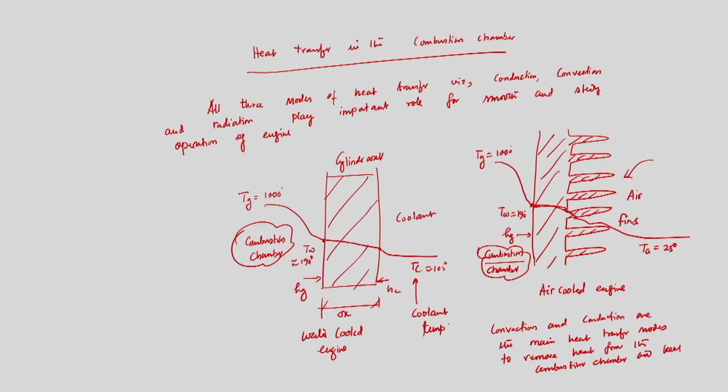And keep the cylinder walls from excessive heating, which in turn may lead to melting. That means if we do not have proper supply of coolant, proper heat transfer from the cylinder walls, there might be a situation that there will be excessive heating within the combustion cylinder walls, which in turn will try to melt the engine cylinder.